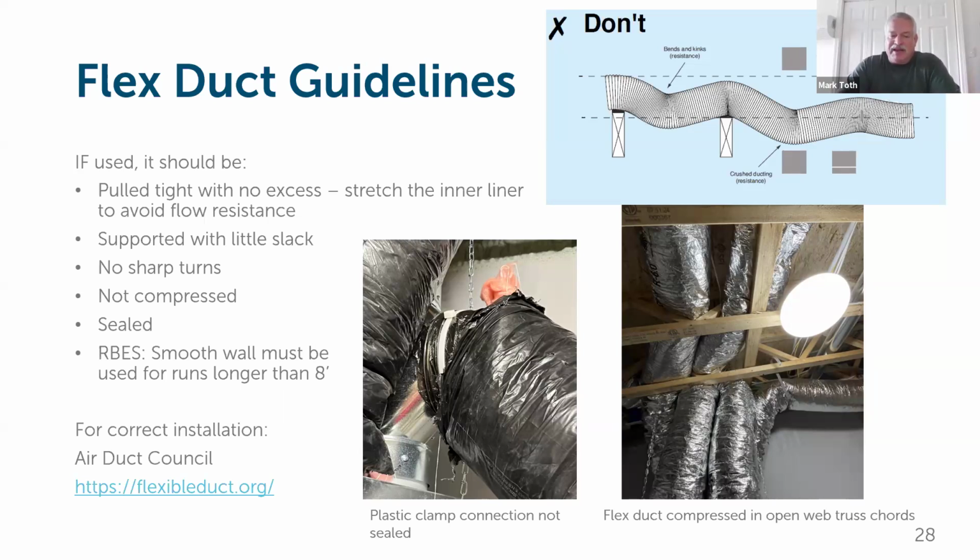So very bad airflow. And I see someone on the bottom say a short piece of flex makes a nice sound damper, and yes, it does, 100%. I've had multiple jobs where you go to a duct system with an ERV, and no one did anything wrong, but for some reason that particular duct system is very noisy. It will sound like a musical instrument sort of thing.